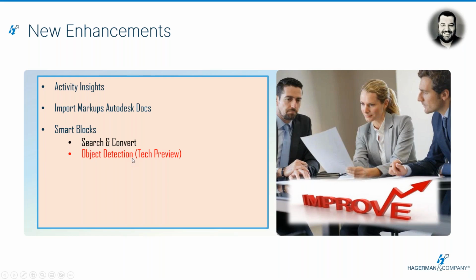It offers the ability for AutoCAD to actively look around, when summoned, for examples where blocks could be used, and it gives you advice like, hey, maybe this can be a block. Because it's a technology preview, in my demonstration I'll show how some of the things it detects may not quite be what I would like or expect, but there are still other entities that I want to bring in and convert as a block.